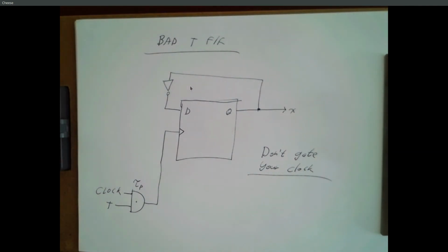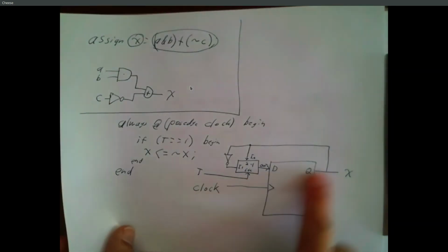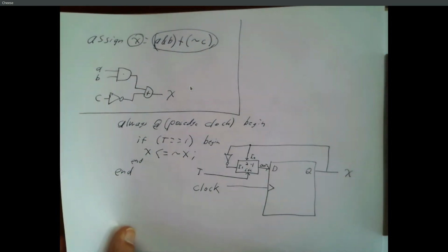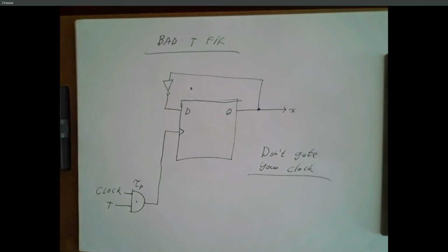All the clocks should go directly into the clock inputs of your flip-flops. And if you want to do something like choose to ignore the behavior of the flip-flop, you have to do something with circuitry. The propagation delays here don't cause me any harm, because that's happening in between the clock ticks. But we want all of our devices to update synchronously. Synchronous design is the name of the game. So if you try to write a circuit like this in a better design tool, it'll actually warn you that you have gates on your clock line. And it gets really unhappy.